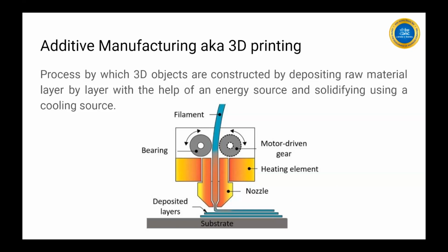Anyway, I'll explain a commonly used 3D printing technology called FDM, fused deposition modeling, and this is an example of that. Before going into that, we will have a molten material and we will deposit it layer by layer, and one layer will be of very minute dimension, say even 10 micron up to, yeah, please.